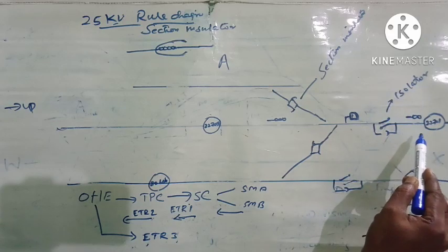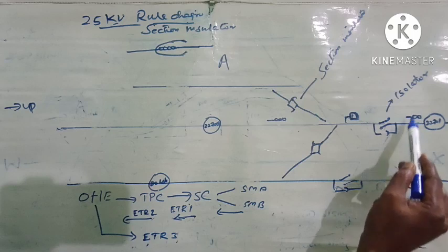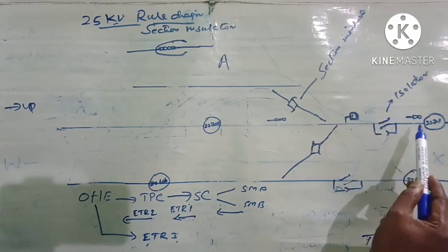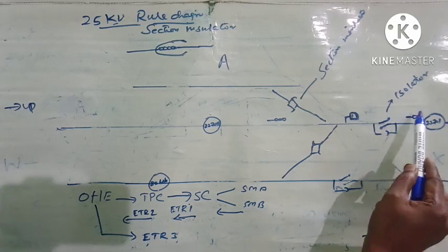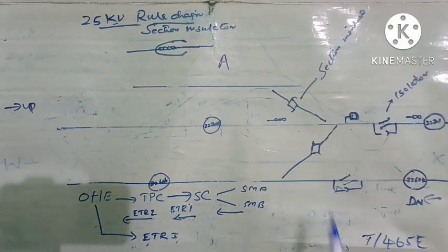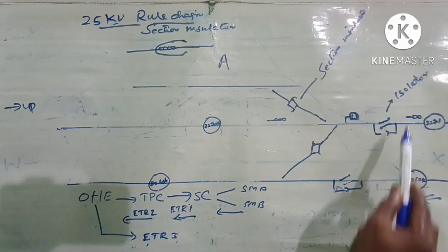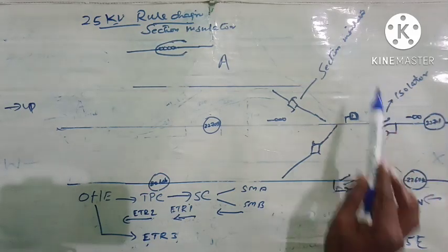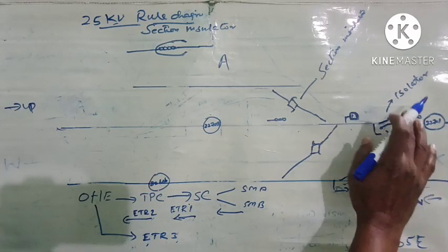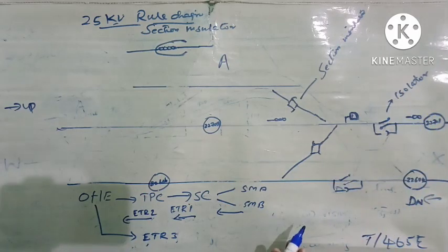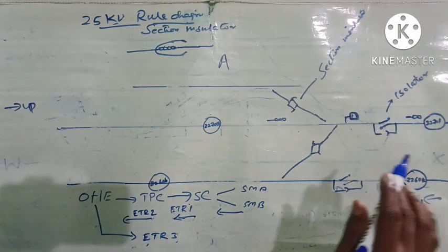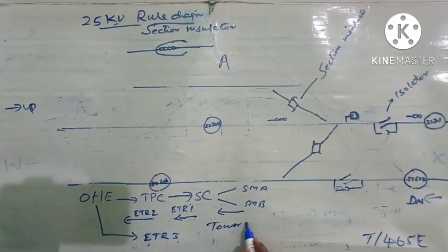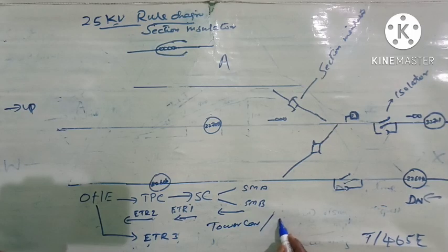Now let us take a case while working with the line block and also power block. The engineering staff is working here with the crane, and suppose it is found that the boom cannot move freely with the OH line above. In that case, the OH line is to be just shifted to a side. OH staff can do it only with the help of a tower car or a ladder trolley.